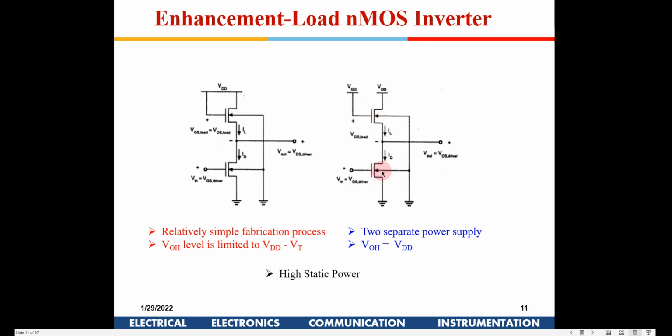Right. So here, if you see in this particular circuit, there were two VDDs used. One was VDD here, and the gate voltage here was VDD plus VTH. Okay, if you do that, then you will get a full VDD here, right? Because the VTH drop is compensated by giving a higher gate voltage in this particular case. So you could do that. So once that is done, you will find VOH is equal to VDD out here, right? But the disadvantage was using two separate power supplies.